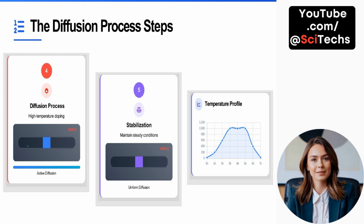On the right, the temperature profile graph illustrates the heating and cooling curve. A gradual ramp-up in the first few hours, a plateau at high temperature during active diffusion and stabilization, followed by a controlled cool-down to prevent wafer stress or damage.